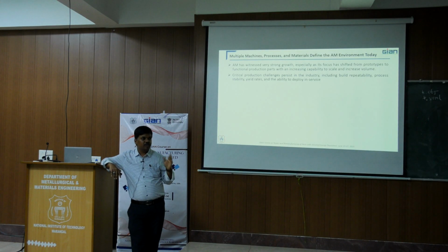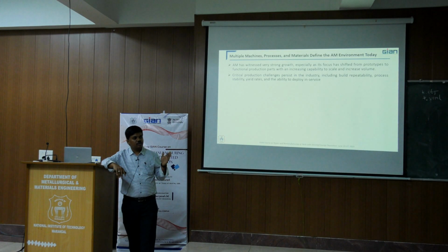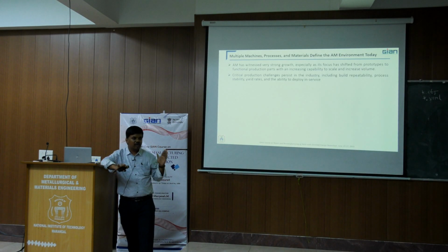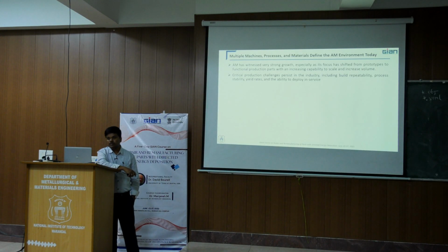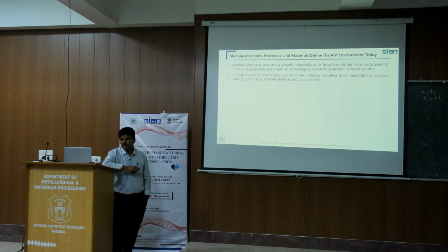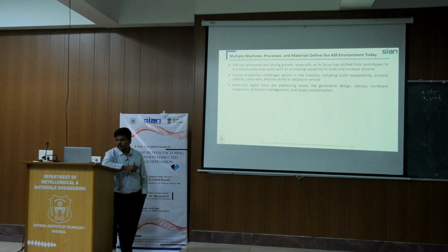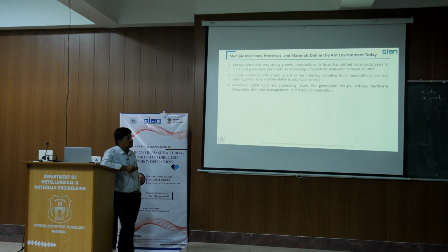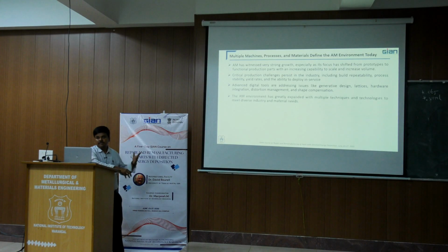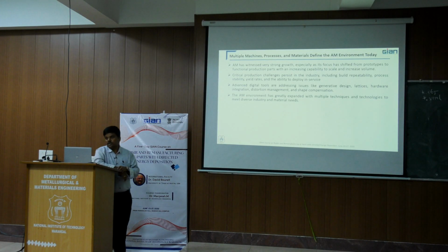That's what we need to see: the quality of powders which we are using for manufacturing and the energy density which we are using for manufacturing the part, whatever machines we are using. That's what the critical issues or challenges still existing. That's where advanced digital tools are addressing these kinds of issues, like generative designs or lattice, or maybe even the hardware integrations, or even maintaining the distortion as well as the shape compensations also.